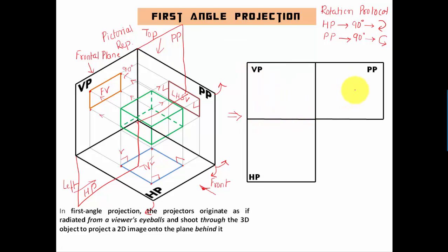So this is going to be your profile plane, okay, and we're going to start off by making this front view initially. You can start off with any view. It is advisable to draw the front view or the top view initially, and then you can get going with the side view. And we're going to know this distance, what this distance is. We're going to make a point, and then we're going to go ahead and make this front view, something like this. So this over here represents the front view, and you can see this projector line over here, this line in the downward direction, and this angle initially was 90 degrees.